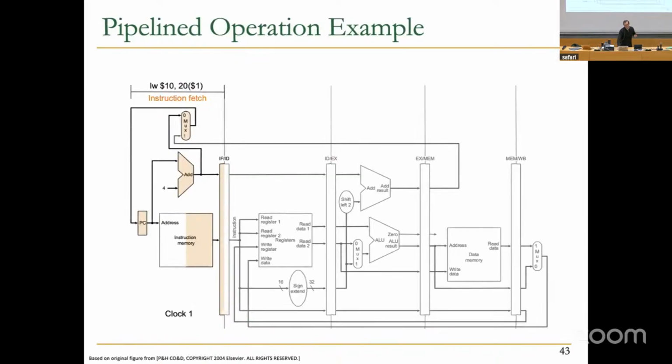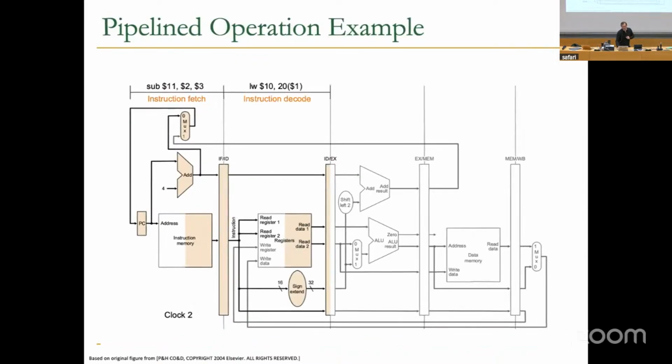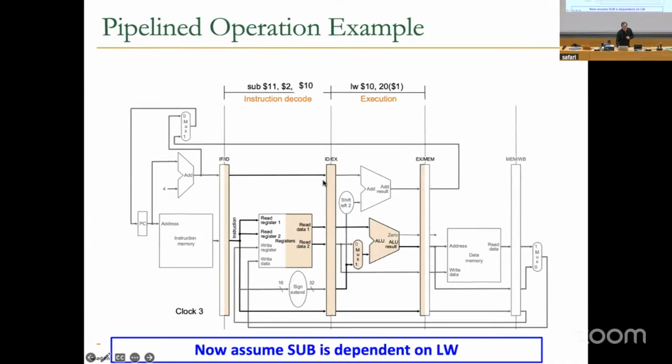Okay, so a pipeline operation, basically, what happens in this case? So subtract, for example. When it gets to this stage, there is some combinational hardware dependence check logic, and we will actually briefly describe that logic later on, that checks whether register 10 is being written to by any instruction over here, over here, over here. So how can you check that? Basically, you get the destination register IDs of instructions here, here, here, and compare them to the source register 10. Okay, this is an equality checker.